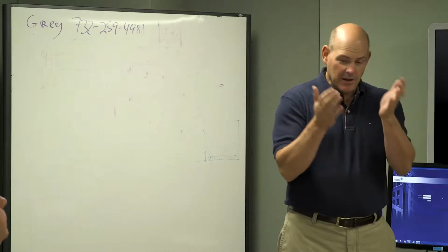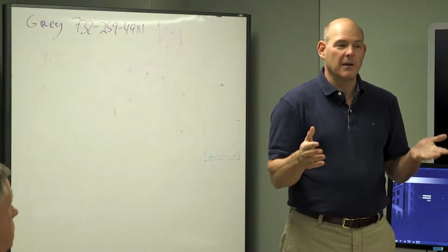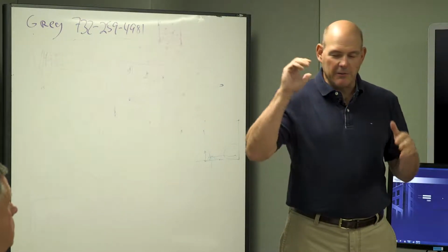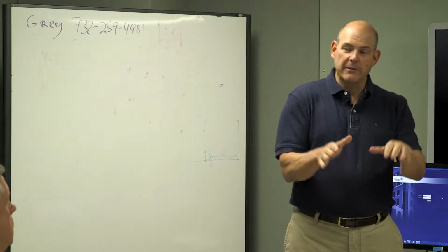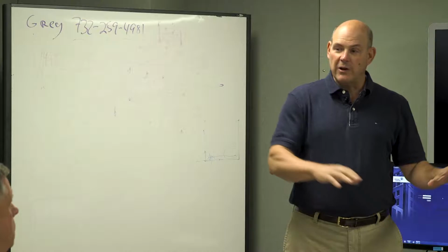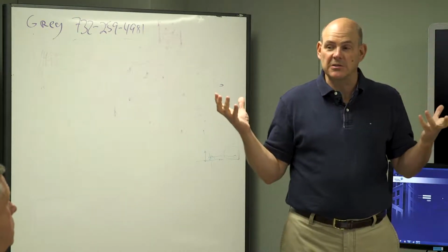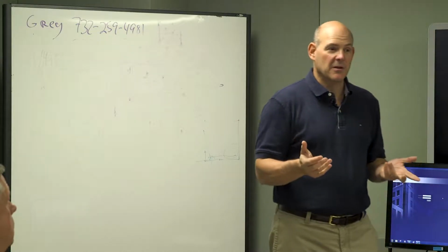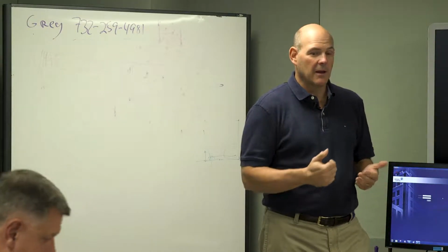The balancer is going to tell me that's the number. The only reason you would change that number is if you have clogged piping or a problem, and you want to lower the number, that'll lower the pumps down. You raise the number, you're going to raise the pumps, and you're going to raise the pressure in the system. So it all depends on if you have an emergency and you want to do something.